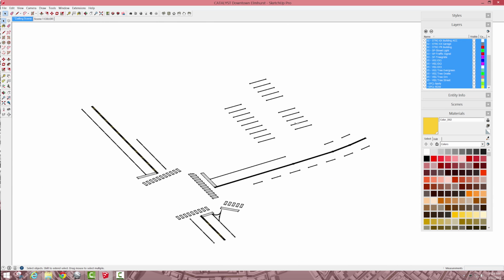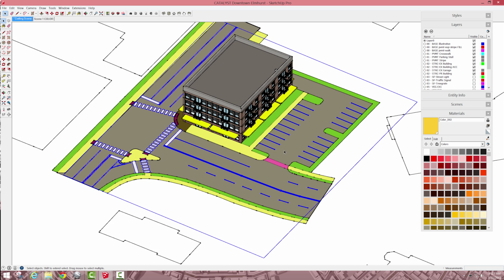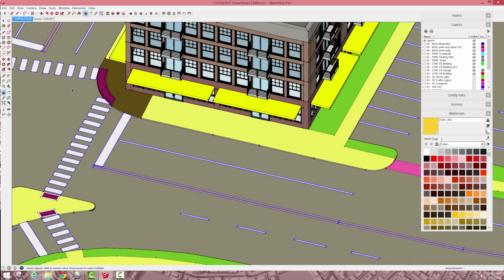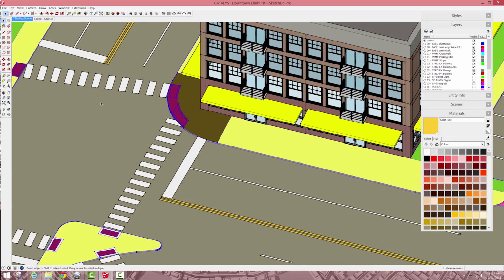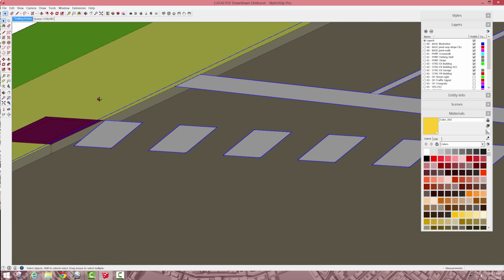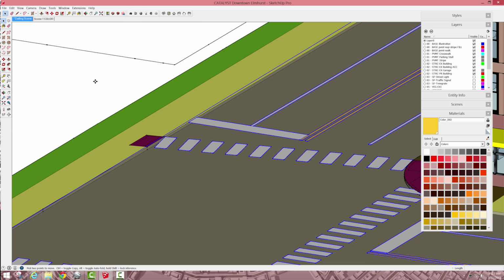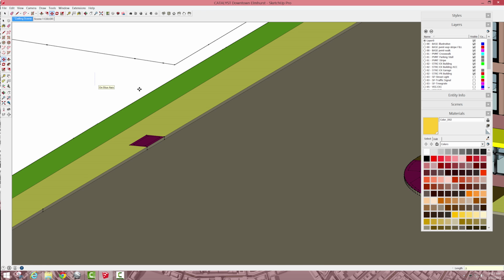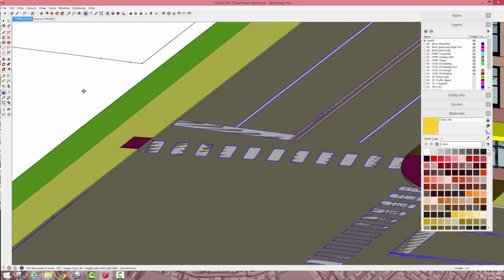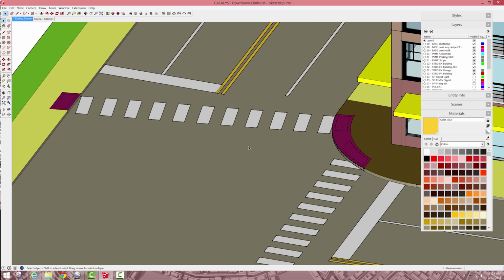And then we'll raise this up, because right now, let's go to our draft mode. So turn all those layers on. Right now there's a little flicker sometimes since these are all on the same plane. Oh, actually no, this is down. So the pavement striping is too high. It's 0.5 down. So I'm going to move it down to 0.5, which is right on the plane with the road. And then we'll raise it like 0.05, just enough where it's up. It'll cast the slightest shadow, so you don't even have to make it 3D like the paint would be.